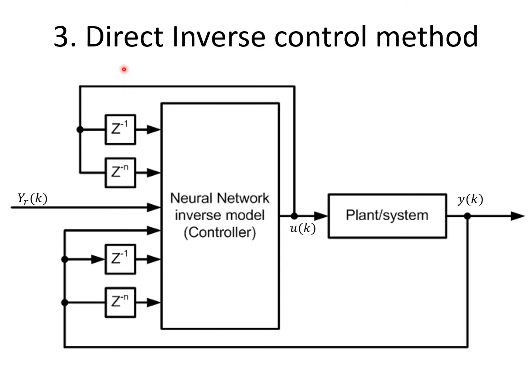And then this is where the direct inverse control method, just like in the specialized method of training, is being trained this way. Once you get the neural network, you put it into this strategy, and you get the direct inverse control method, the controller controlling the plant. So the inverse model of the plant is basically the controller itself. If this is a perfect inverse model, it is the perfect controller for the plant. Okay, this is dynamic. Always remember, this controls the dynamics.